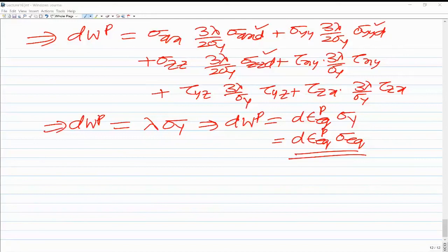When we are using general elements like a quadrilateral element, a four-noded, 3 degree of freedom element, there will be 12 shape functions. Will these shape functions change for every element? If you write these shape functions in terms of a local xy coordinate with origin, let's say, at the left bottom node of each element, then the shape functions would be the same.